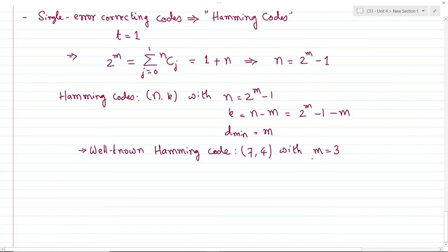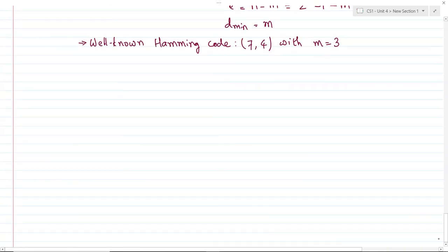All along this discussion we have talked about FEC codes, that is, forward error correcting codes. The classes that we defined as block codes and convolution codes are classes of forward error correcting codes, in the sense that the receiver doesn't give back any information to the transmitter that it has detected and corrected errors. But there could exist some systems, not part of our discussion, just to state that there is another class of mechanism known as ARQ.